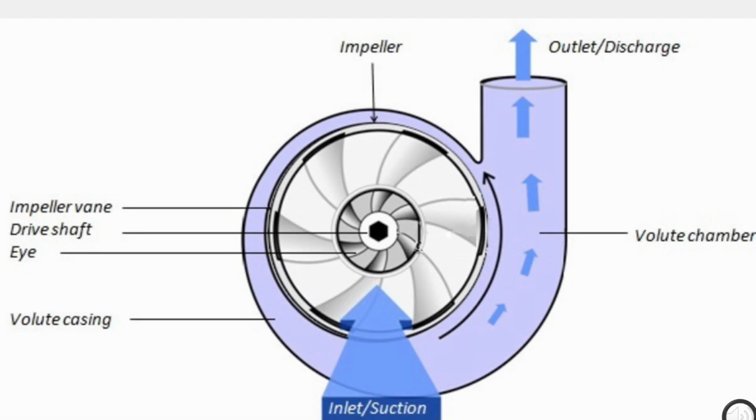So, how exactly does a centrifugal pump work? At the heart of the process is the impeller, which has a series of curved vanes. Fluid enters the impeller at its eye location. When the impeller rotates at higher speed, it accelerates the fluid velocity into the volute section of the casing. The volute chamber in the casing then facilitates the discharge of the fluid out of the pump.